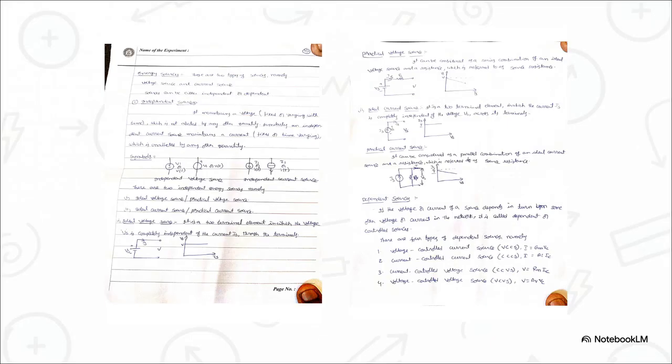So far, we've been talking about this perfect, theoretical textbook realm where sources just work flawlessly forever. But reality is a bit messier. An ideal source on a graph holds a perfect horizontal line of voltage. It literally never wavers, even if you draw infinite current from it. But for a practical source, as you draw more current, the voltage slowly starts to sag.